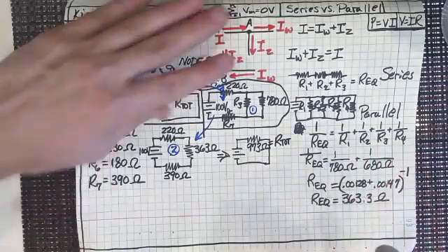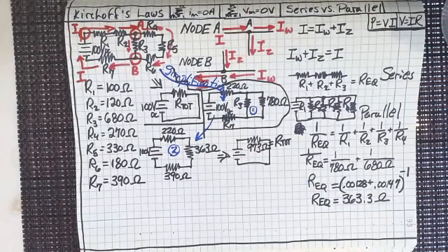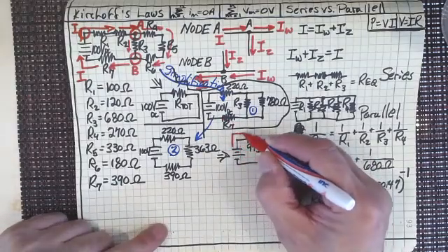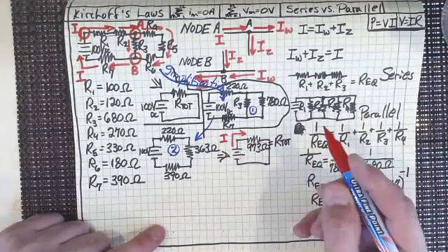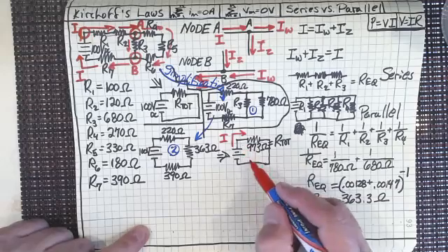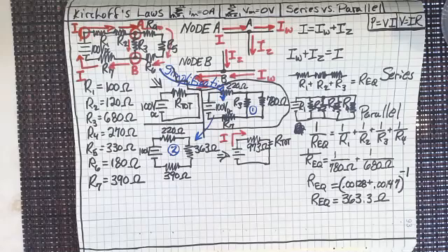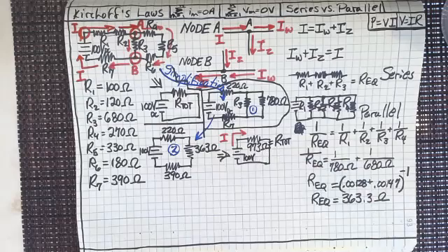And that's the first thing that you want to work with. The first thing is that we want to find out what is the current that is coming out of that power supply, right? And now we can do it because we know that what that power supply sees when it's figuring out the current I is 100 volts and a 973 ohm resistor, right? So that's almost 1,000 ohms, isn't it?